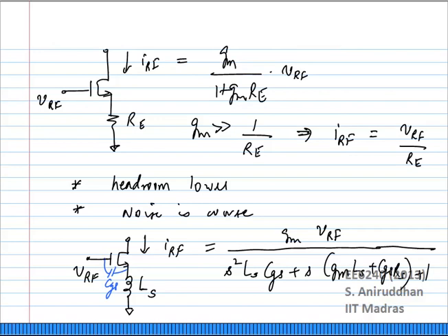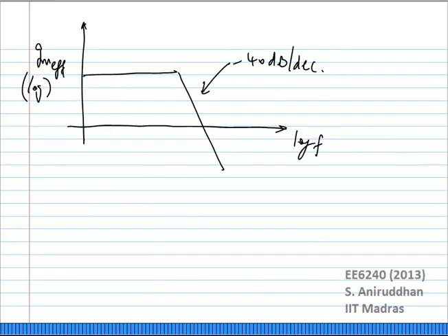Obviously, for higher frequencies, it is expected that it gives you better rejection, because the impedance of the inductance increases with frequency, so it is as if you have a frequency dependent degeneration. At very high frequencies, the inductor acts as an open, therefore you have very little gain. This is obviously expected. So, good attenuation at higher frequencies.